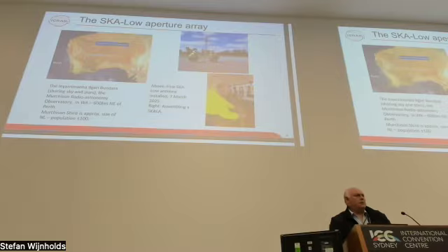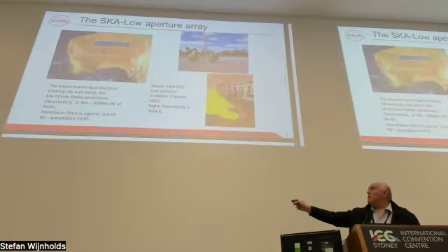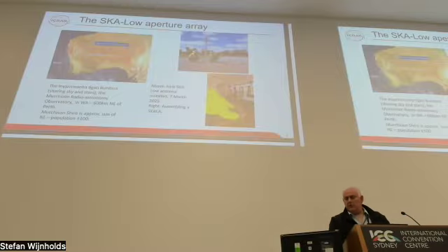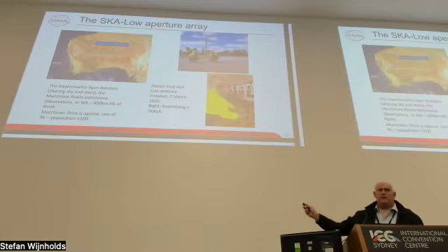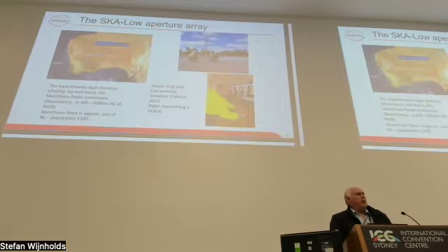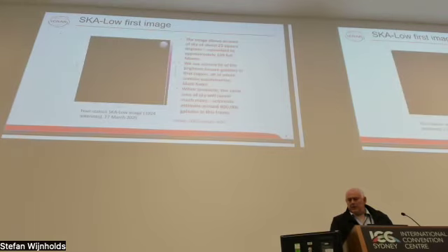Again, if you weren't in the talk yesterday, the SKA low is in the area of the Murchison, right up over there. I won't run through all the material I spoke about, except to say that the receiving element is the Scala. It's a dual polarized log periodic dipole array. It's been through a number of design iterations. This is version 4.2 that's actually deployed on site, and it's identical to our simulation model of the 4.1. From an electromagnetic viewpoint, it has some production enhancements. I'm going to skip over that as well.